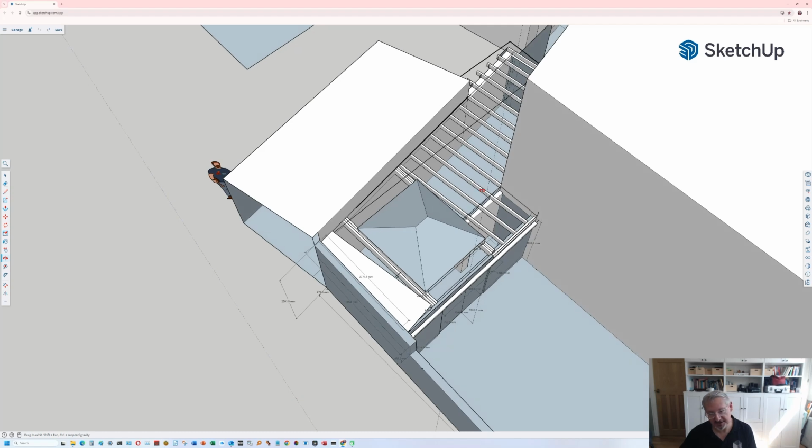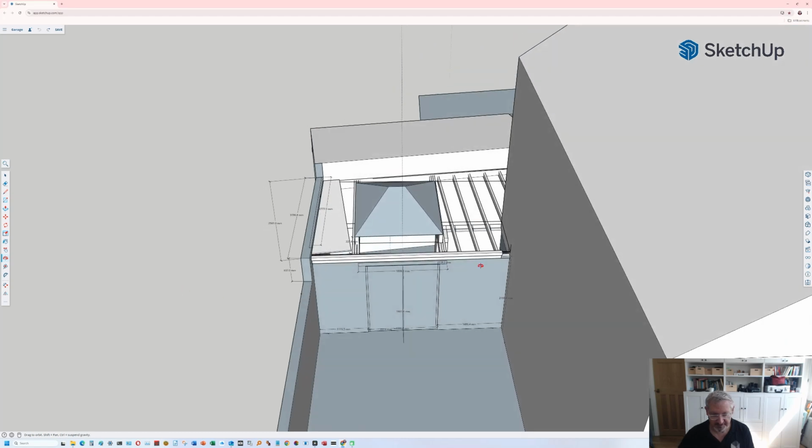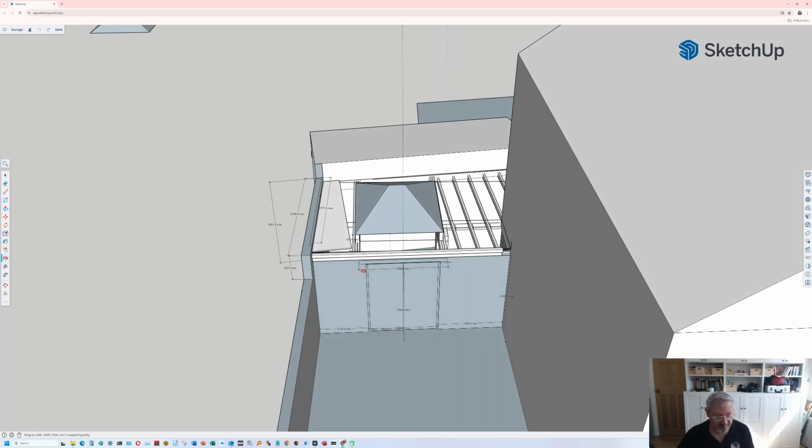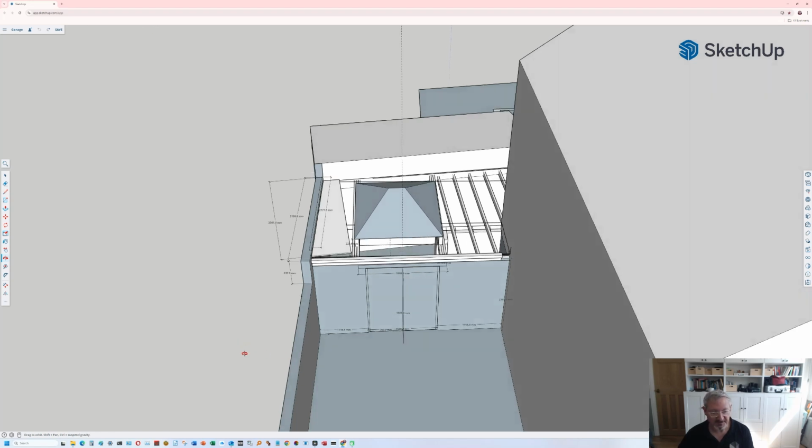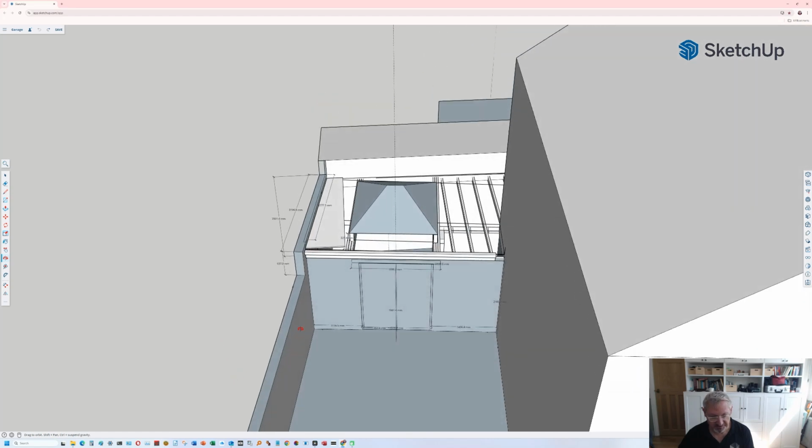So what we're going to do is build a brick wall, double thickness solid brick wall here, with a double door entry, which is going to be roughly 6 foot, just under 6 foot wide. So we're going to have 2 stable doors there, and a lintel over, and a thick double brick wall with no insulation in it, on a foundation, and that closes this whole gap here.